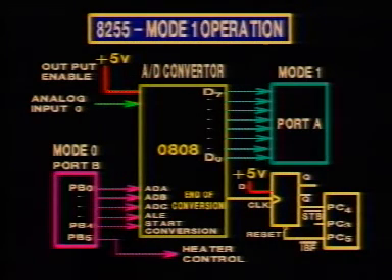The inverted output of the latch is applied as strobe input to IC 8255. The input buffer full signal resets this strobe input. The cycle is again started by applying a new start conversion pulse.